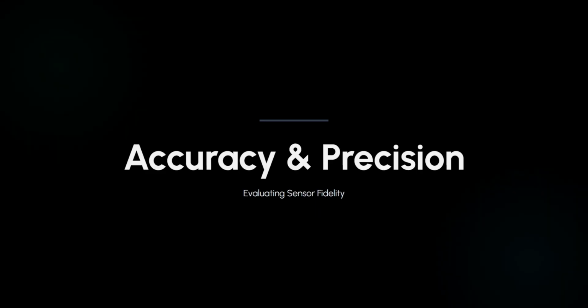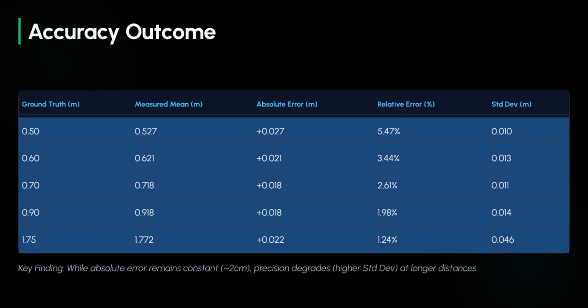Next, we evaluated accuracy. We tested the sensor against ground truth from 0.5 to 1.75 meters. Refer to the graph on slide 7. The sensor shows excellent linearity with an R-squared of nearly 1. However, we identified a systematic error. There is a consistent positive offset of plus 2.2 centimeters across all distances. This is a calibration bias that should be corrected in software. Precision remains stable at short range but degrades significantly at 1.75 meters, showing that noise increases with distance.